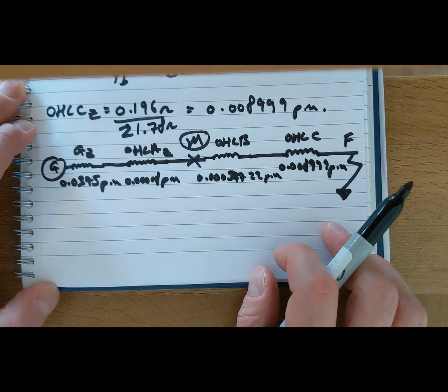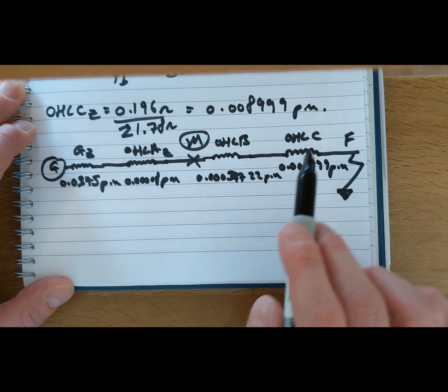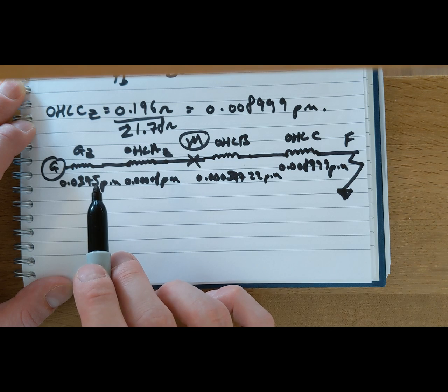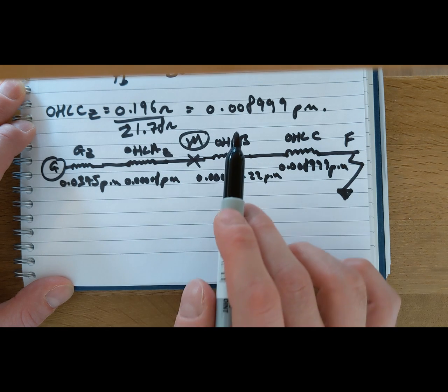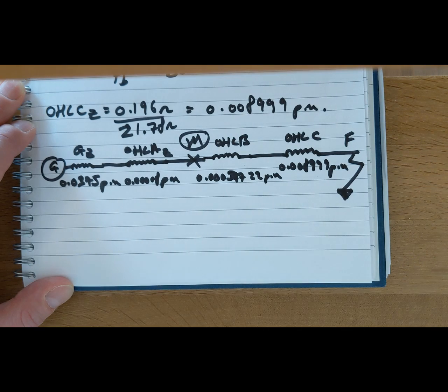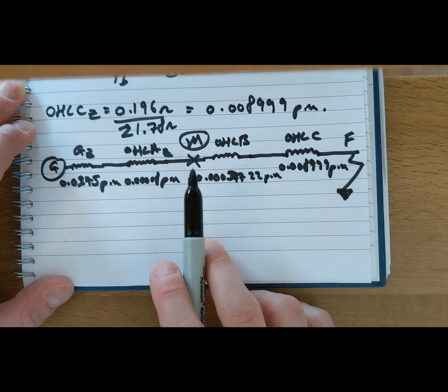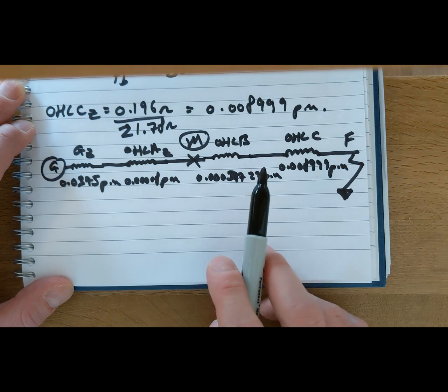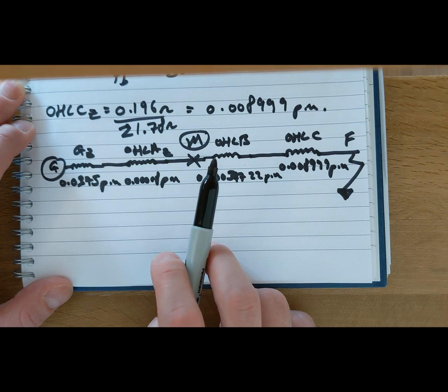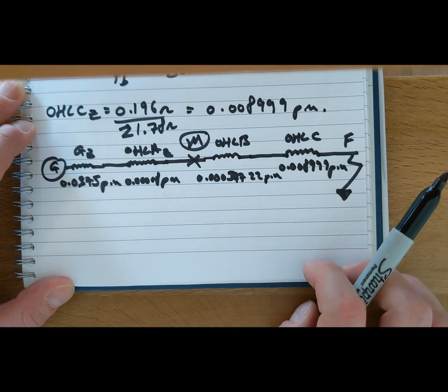And it's very simple to calculate the total impedance. Now that we can neglect transformers, it's simply the impedance of the generator plus the impedance of overhead line A plus the impedance of overhead line B plus the impedance of overhead line C. Whereas if we were going to do this in real values, we'd obviously have to reflect these impedances through the transformers by the square of the turns ratio, which is very laborious, and then we would have to work out the step up and step down of all the voltages and currents.